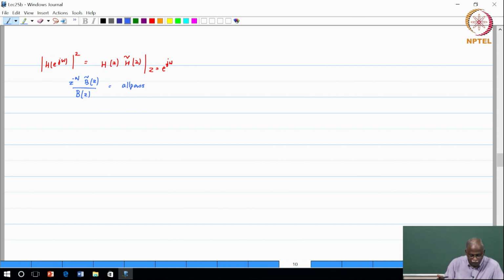Therefore, this is the form of the transfer functions that we are interested in. The other element which also emerges from here is that if you have all pass functions and they have the structure shown above, this also means that if I have a pole at z0, then this necessarily requires, because of the structure, a zero corresponding to it, because they are both of the same polynomial.